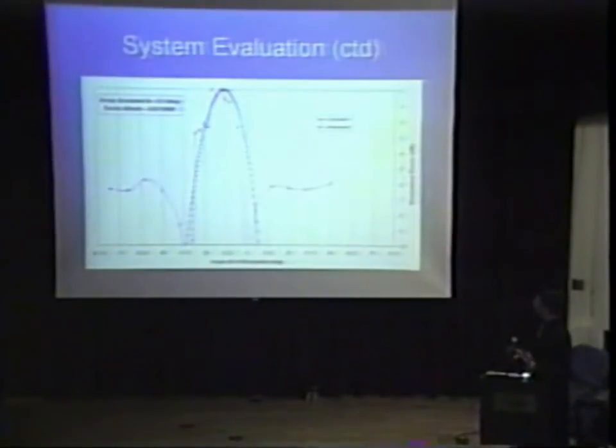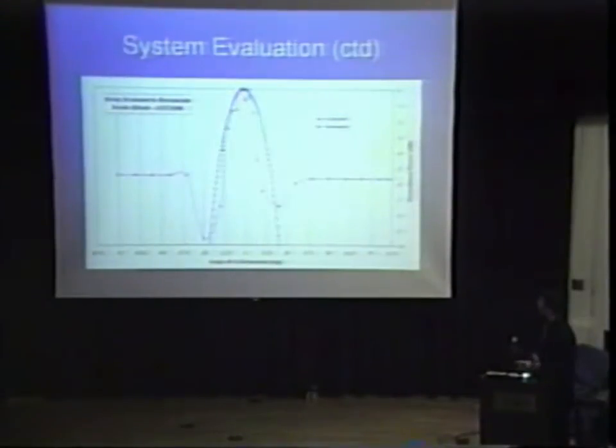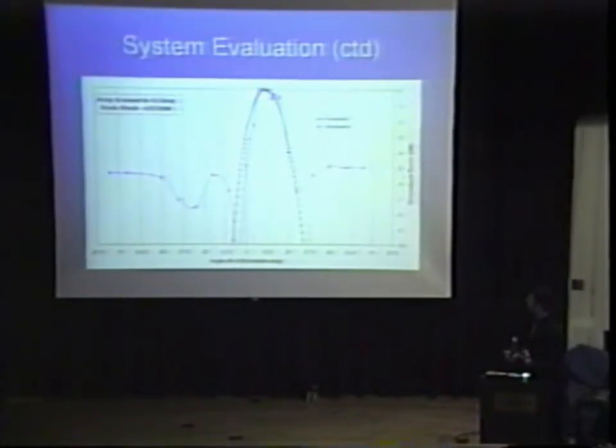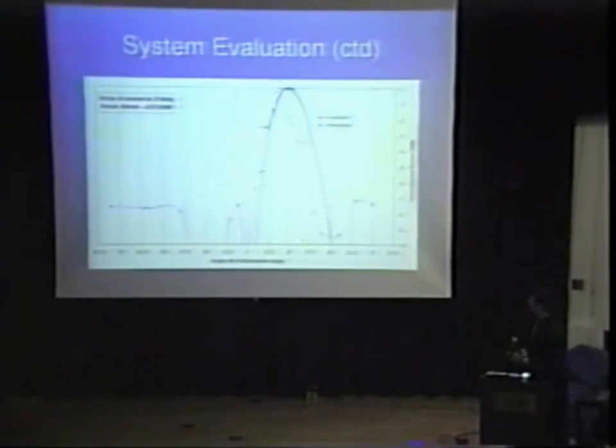As we scan, we go to minus 12.5. The beam also agrees very well with what was expected. Broadside, you can see right here, it's sticking straight out from the antenna. Moving to 12.5, this was also very good. And then 25 was a little bit off, but that could have to do with more measurement error.